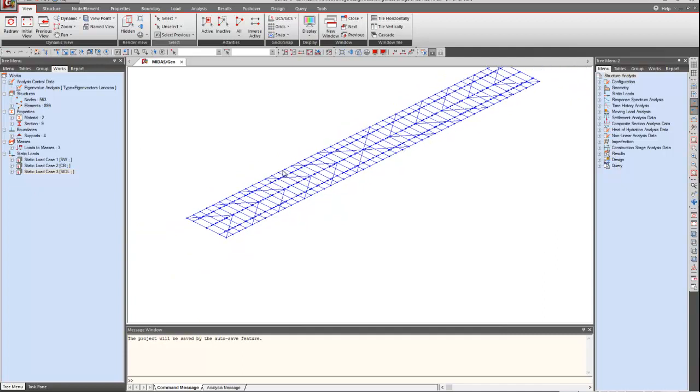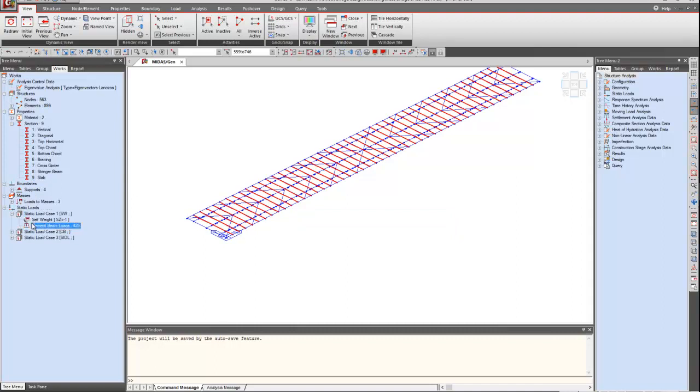Basically, how I have modeled this is, these three are my main stringer beams which are going to run throughout the bridge, and these 12 members are my cross girders. So these are the main elements of the bottom of my deck. And these others are cross girders. And now, how I have modeled the slab is, if you see my loading, here I have applied the dead load of the slab on my stringer beams.